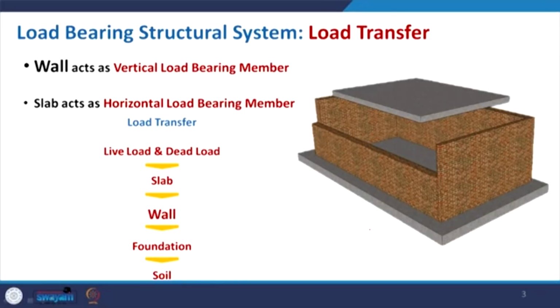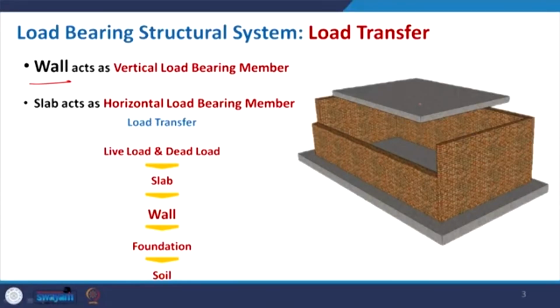So, with that we proceed. Basically, how do they transfer the load? The wall acts as the structural, supporting element, and the slab here is the supported one. All the load on the slab, all these horizontal loads, will then transfer to the wall, the adjoining wall. Adequately, the thickness of the wall should be a little bit thicker than the normal frame structure wall or partition wall, because this is taking the load.